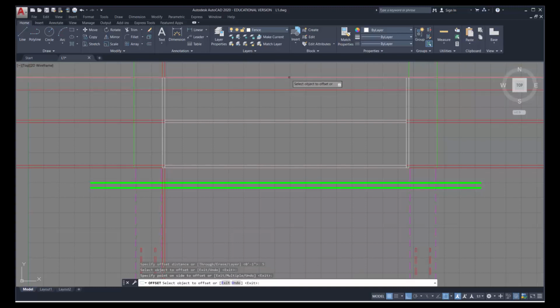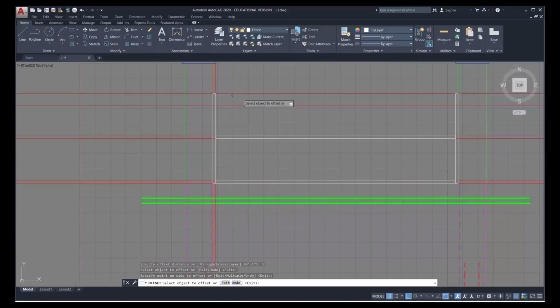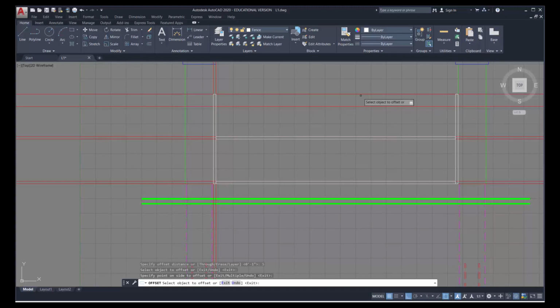and click down. Now this technique we're presenting here is really good if you have a bunch of columns that aren't exactly the same distance apart. I don't want to have the same radius arc between each one, because if I look down the fence line, I'll actually see the bottom of that arc different in each object. So let's say they're out by 2 or 3, 4 inches between each of the columns. I want to specify an arc between a site measured column so the dip looks exactly the same between each of these columns. So I specified a 5-inch dip here.